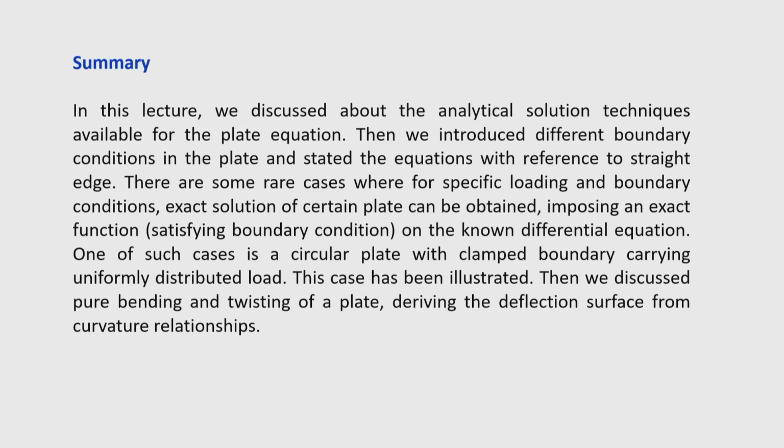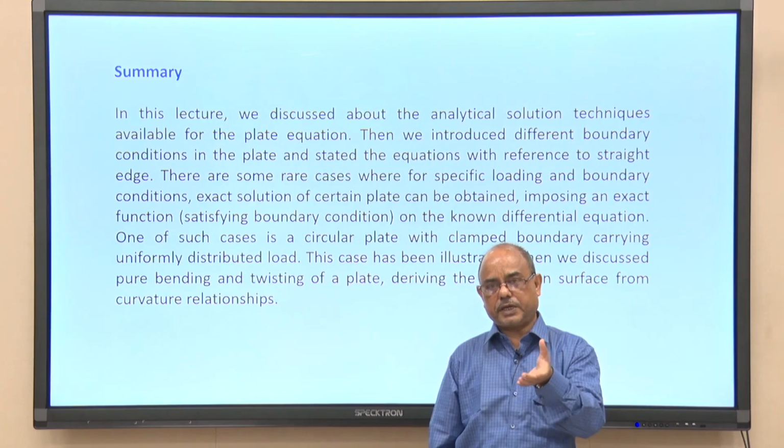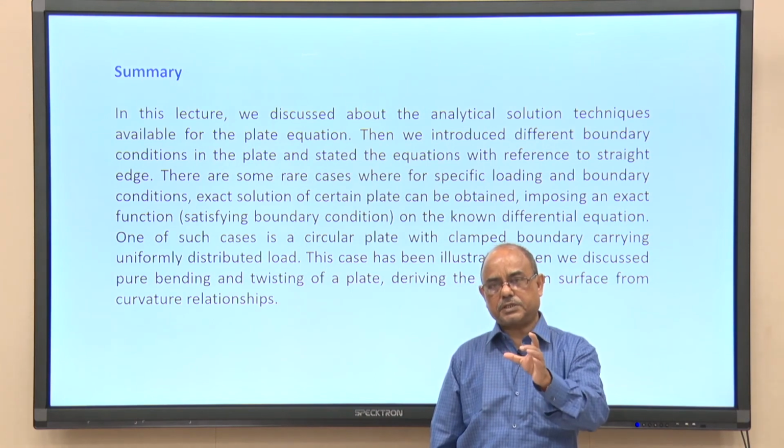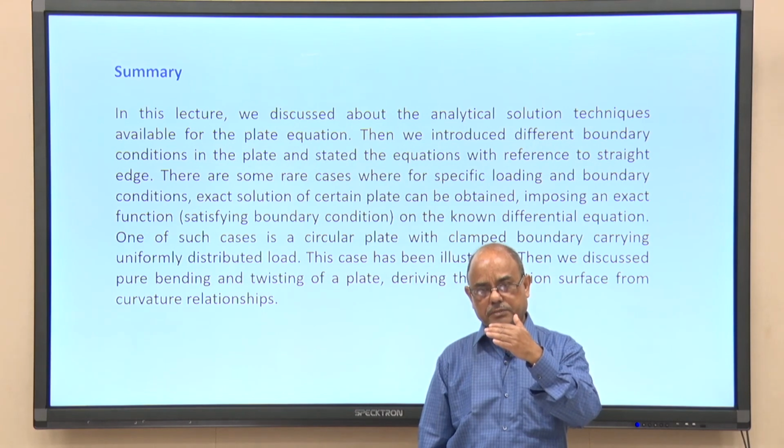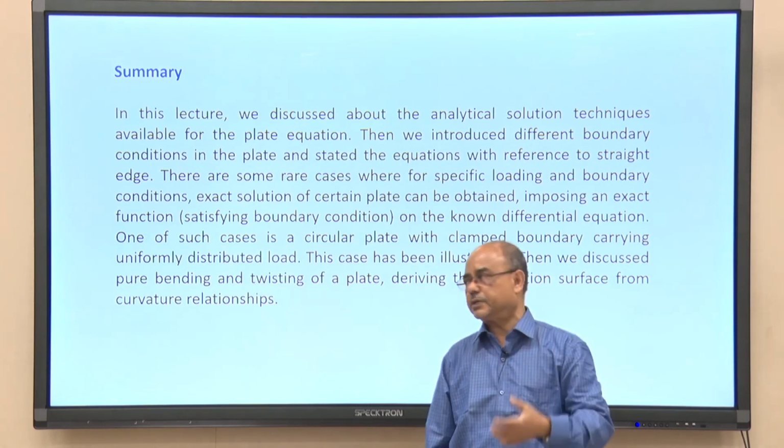As usual, in case of a beam also we have seen that deflection decreases if we increase the depth of the beam. Here also in the plate equation we have seen that deflection decreases when the thickness of the plate is increased, because in the flexural rigidity of the plate the h cube term is appearing. So, there is a similarity between the beam and the plate also.